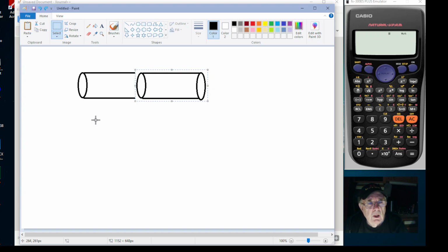So we want the greatest efficiency we can from the energy coming out of the back of our radio to get to our antenna system. And we can do that by making sure that we have a good impedance match between the radio and the antenna system.